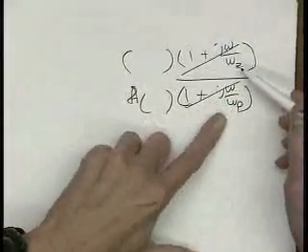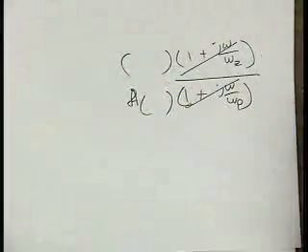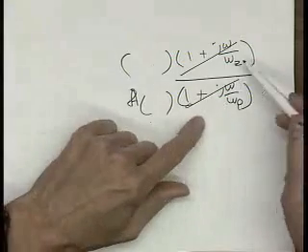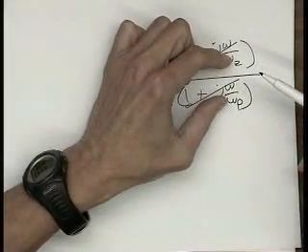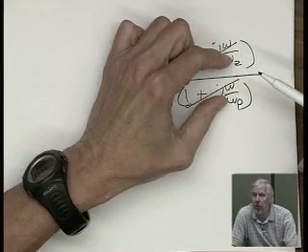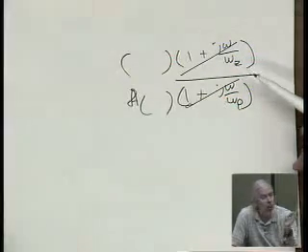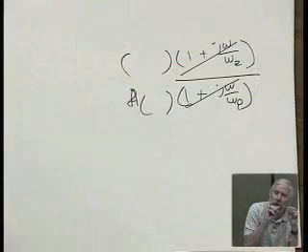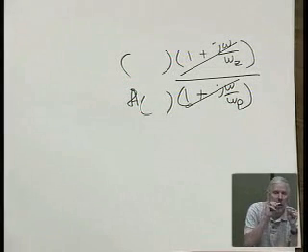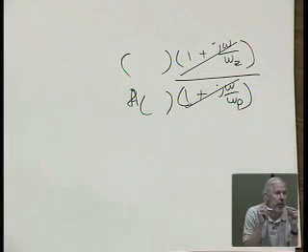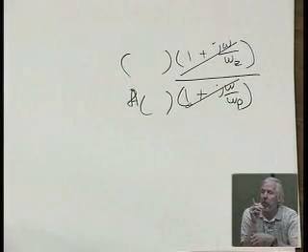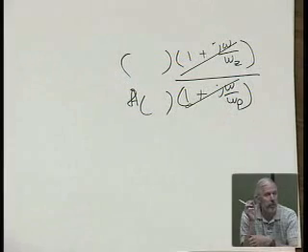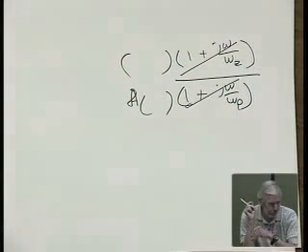But if they're very close to each other, within a small fraction of a percent, these coupled poles and zeros will have no effect on your transfer function. So effectively, look at the poles and zeros list, and any pole that's about the same as a zero, just cancel those out because they're not important. It's just coming from the finite accuracy of the SPICE root solver. So that's another point.